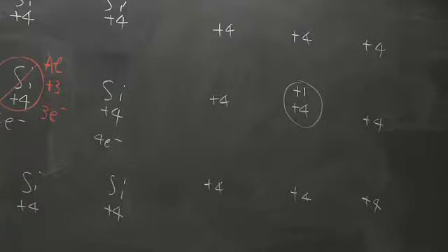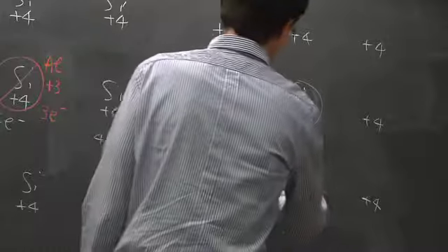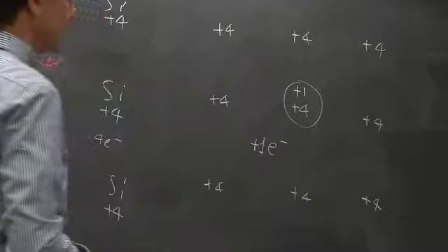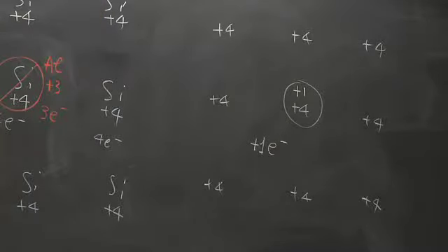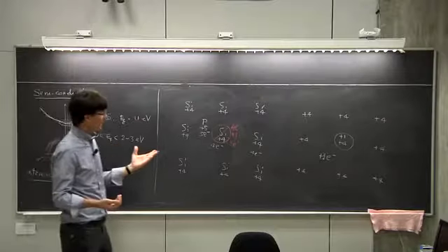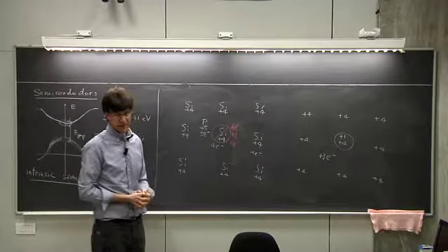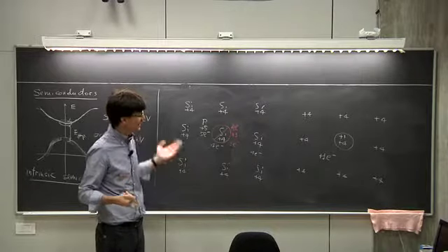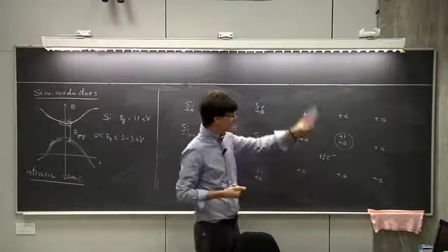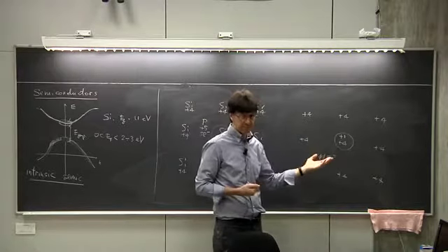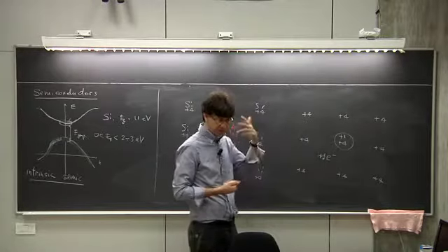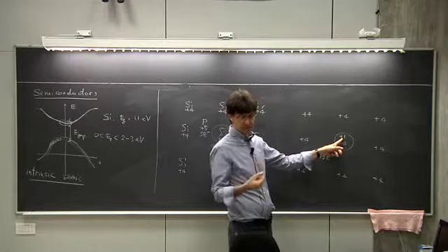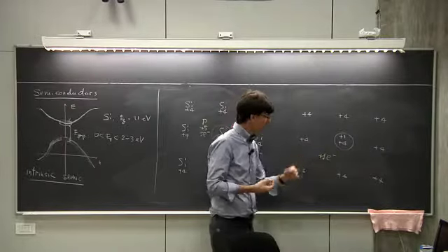The other thing I need to do is to add 1 electron to my system. If I do this, I've done exactly what the addition of a phosphorus atom does. Instead of adding a phosphorus atom, I can say, well, my crystal is made of silicon atoms, but on top of that, I'm perturbing my system, theoretically, of course, by adding 1 charge in the nuclear potential of silicon and adding 1 electron to my system.